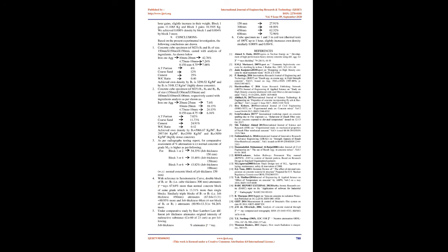These concretes contain boron for neutron absorption and hydrogen for neutron attenuation. The barite ore is also a good gamma attenuator. The thermal neutron absorption properties of concrete can be greatly enhanced by the addition of boron compounds. Hydrogen in fixed water, hydrated, and free water in the pores of concrete serves as a good neutron shield.